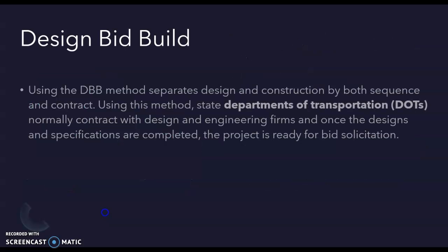Design bid build. Using the design bid build method separates design and construction by both sequence and contract. Using this method, state departments of transportation normally contract with design and engineering firms, and once the designs and specifications are completed, the project is ready for bid solicitation.